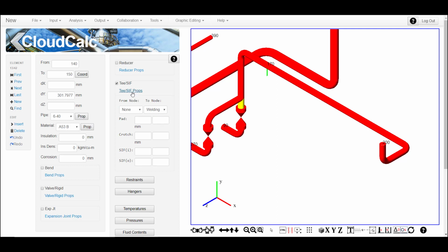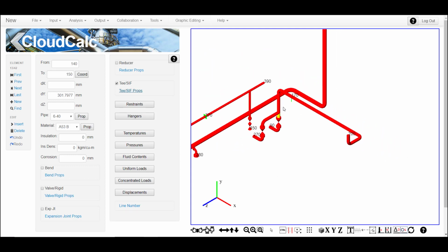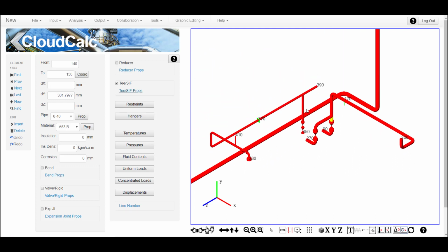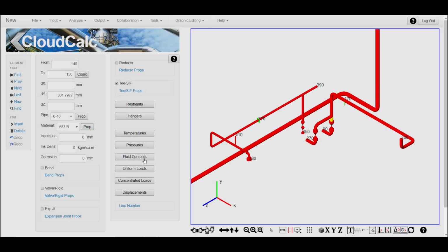Every PCF file varies in how much and what type of data it has available. They may include wall thickness, material type, temperatures, pressures, fluid, and/or insulation data. At best, the model may be fully ready for analysis. In our case, you see that the operating loads were not imported, so we will have to add those manually.